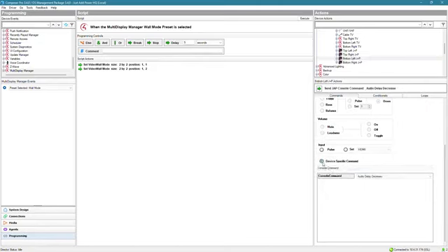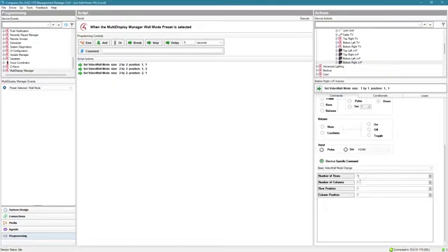Bottom left, device specific, basic video wall mode change, 2x2 wall, row 2, because it's below the left TV. Drag that over. And lastly, our bottom right, 2 rows, 2 columns, and it is the second row, second position. Drag that over. So now we've got our macro to build a full wall out of the 4 TVs that we have. And if you want to test it live right now, you just go up here and hit the execute button, and it goes into wall mode immediately.